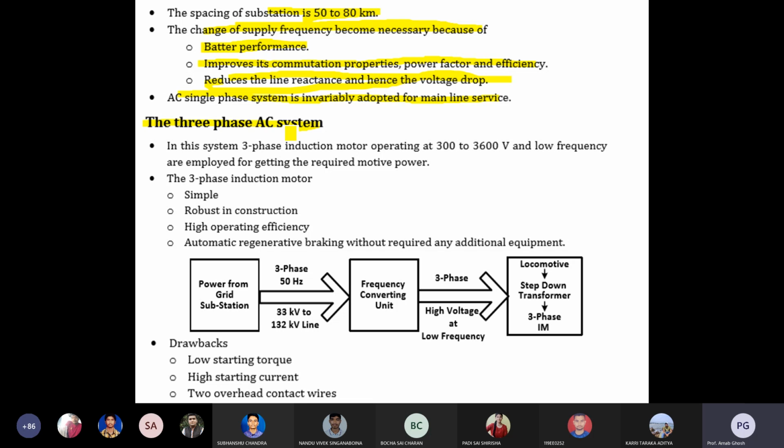The pantograph can collect the power directly from here. But the main issue is that with three phase there is a huge chance of unbalancing. Unbalancing means there is unnecessary current flow between two phases. That is not acceptable. If any faults are observed, the zero sequence component may cause other issues.